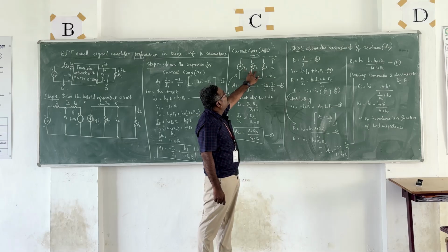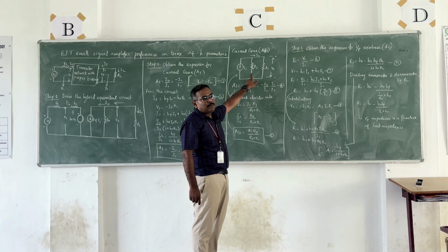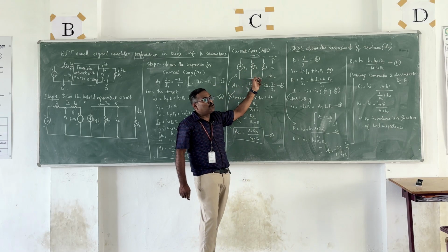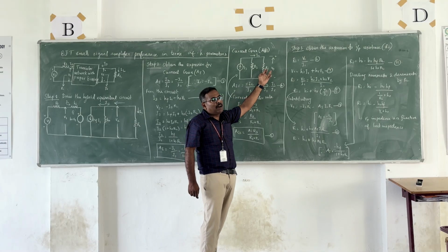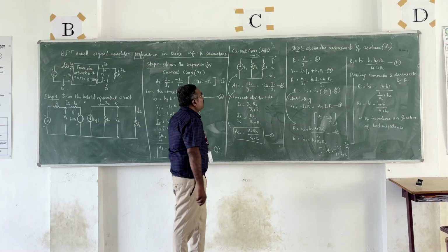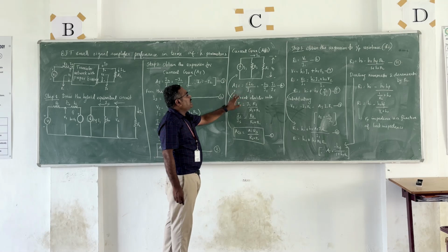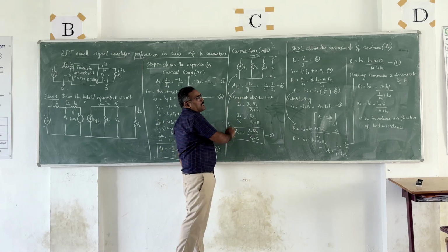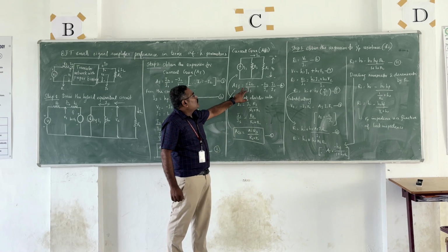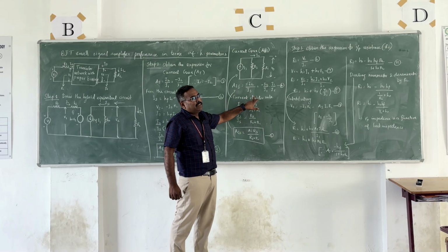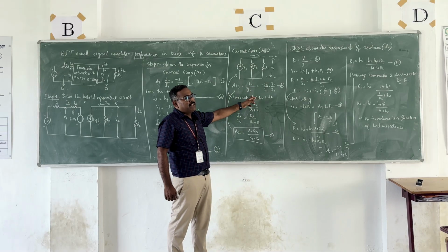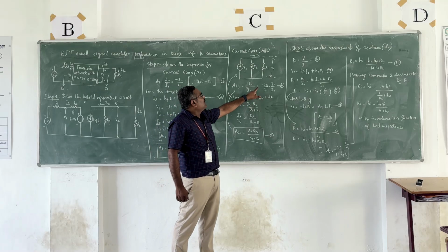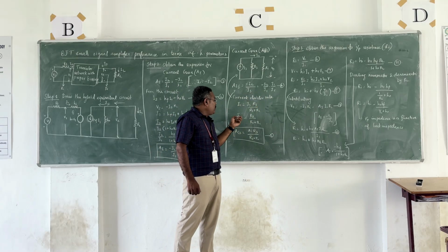So Rs, the source resistance, will be transformed into parallel to this current source, and this one is the actual Ri value. Okay. Now AIs, since it is a current source, we differentiate it with IS. So minus I2 divided by IS. In place of I1 we write the source current. But we have formulas for I2 divided by I1.